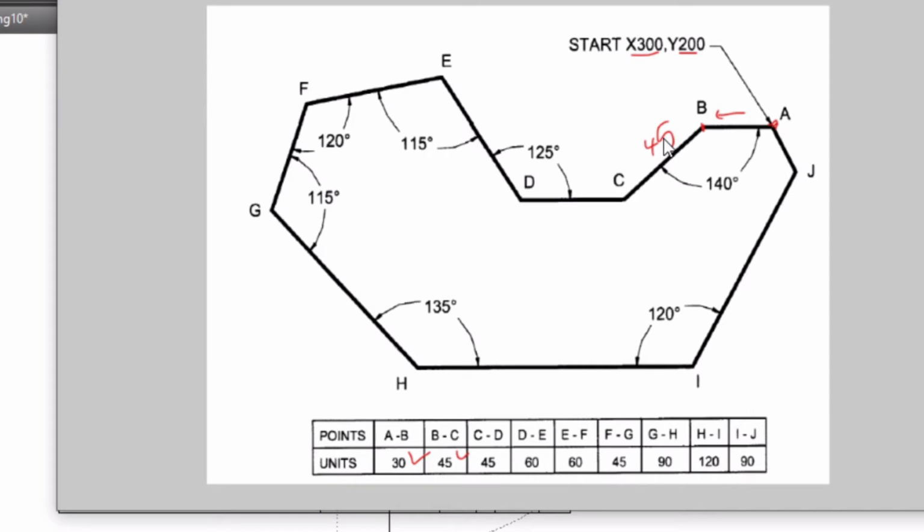If you use my previous technique of finding the 3 o'clock line, I mean the 0 degree line, and it goes clockwise, you put negative 140 degrees so that it takes the clockwise direction and you get that line. That's it. But there is another way in AutoCAD. Without thinking whether it is clockwise or anti-clockwise, whatever the direction it goes, you can make use of this technique, which is called polar tracking.